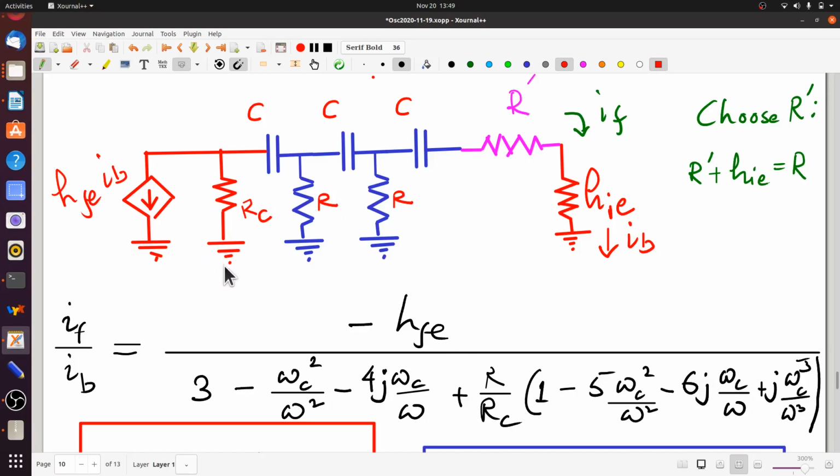Now, of course, for this circuit to be able to self-sustain, it has to be consistent with IF being the same as the current IB. So whatever current is here, that essentially is amplified here, and that amplified version produces this current, which is itself. So you need IF by IB, which is really beta A for this circuit, to be equal to 1.